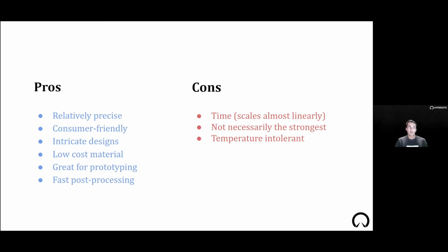Some of the cons, though: it does take a while to print a part, especially if it has a high infill density, because that just means it's got a lot of layers it has to go through. And so that's a trade-off for printing a part you want to be strong. It would be strong, but it's going to take a while to get there.